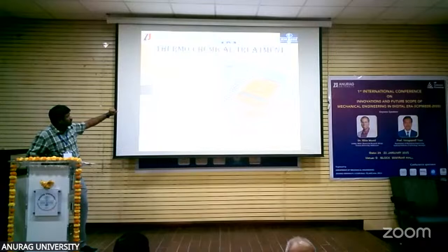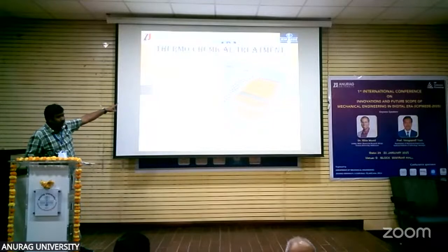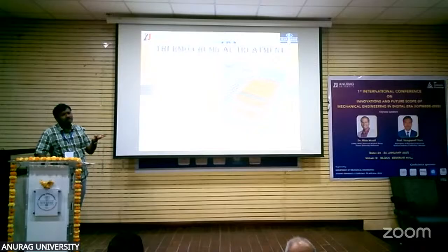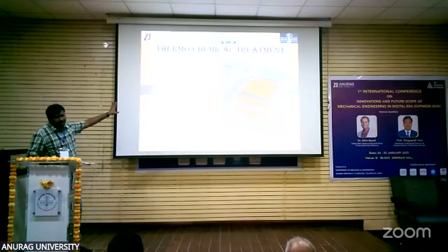I kept them in a solution of sodium hydroxide and sodium sulfate in distilled water, 2.5 moles of sodium hydroxide and 0.4 moles of sodium sulfate, for certain periods of time: 5 hours, 17 hours, and 24 hours. These are three stages: thermochemical treatment 1, 2, and 3.